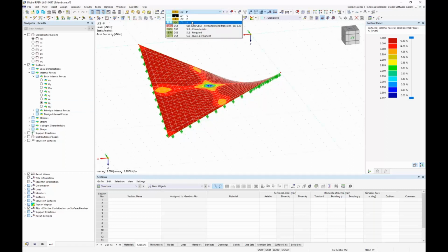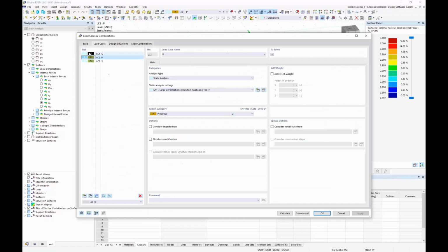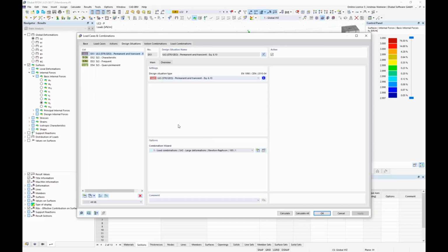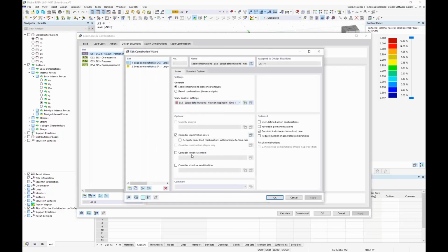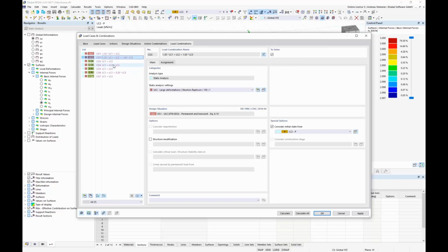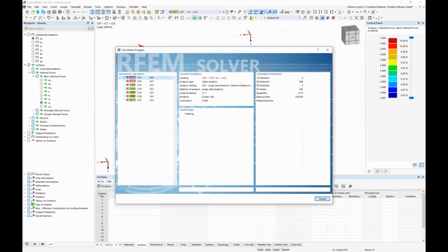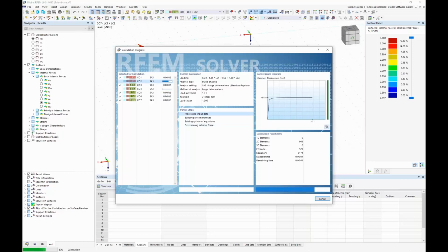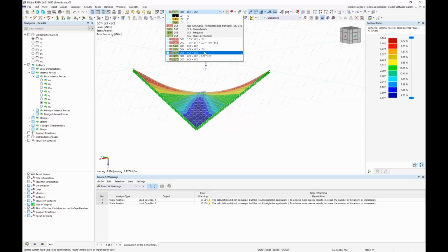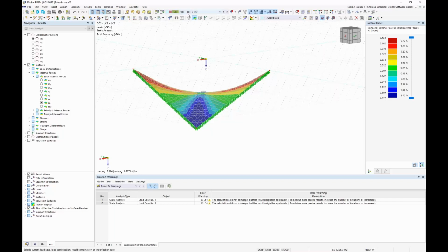And if you want to combine all these 3 load cases in combinations as standard recommendation, you go into the load case and combination menu, define the combination wizard setting, which is on by default, and tell the wizard, please assign always the initial state, the shape from load case 2. Not more. In this case, it's enough. And if we go to load combinations, you see the program assigns even for this surface structure this shape from load case 2. And if we run the analysis, the program uses this shape and detects the forces. As you see, now if we go maybe to the characteristic solution, we have here maybe shape plus self-weight.